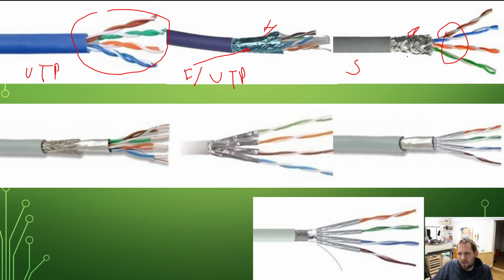However, the braid is going to be a lot better. It's a lot stronger, it's thicker. In theory, it is actually completely wrapped around it with everything touching, where the foil in your hand, as it wraps around, might just loop underneath and you might not have a great connection right there. So just something that you might want to keep in the back of your mind.